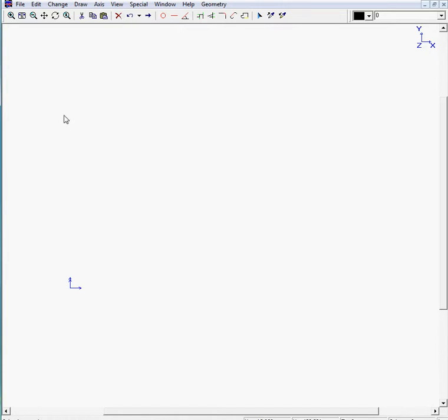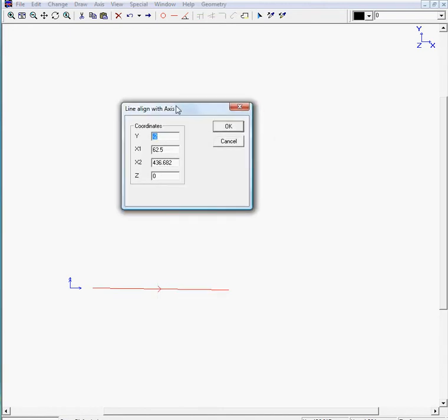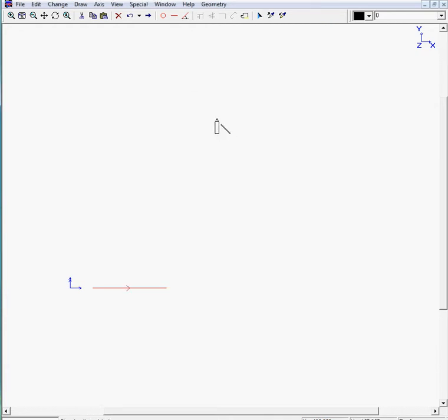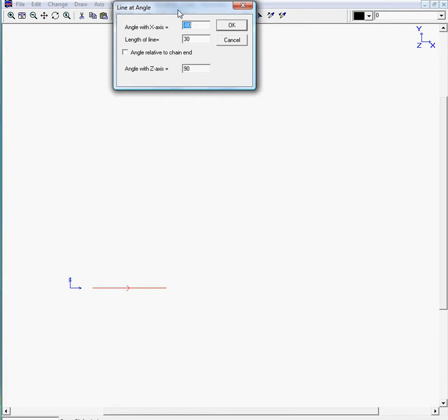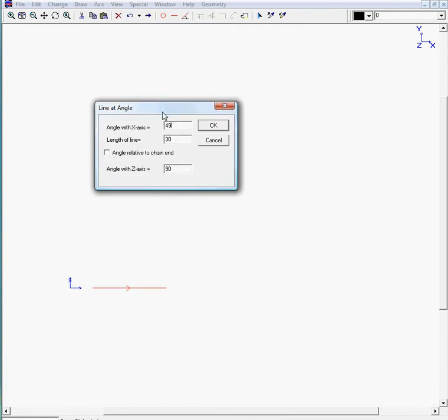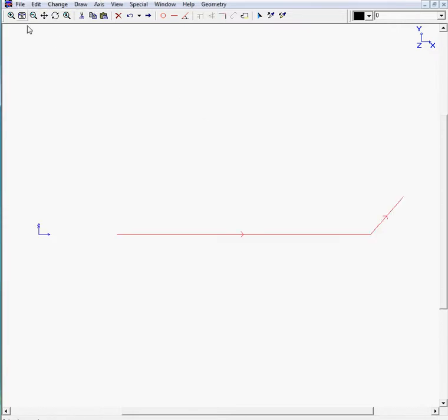We will start with the first horizontal line. As you can see, the reference point lies at the bottom on the left. So we draw our first line from left to right. The y value is 0. In this case, the x2 is important, as from there we need to draw a line angle. So this is 265. We can then move to line angle, which has an angle of 49 degrees. The length is unknown, but we can enter 40, for example. And we see our line angle.